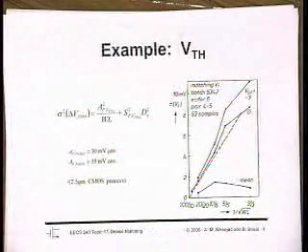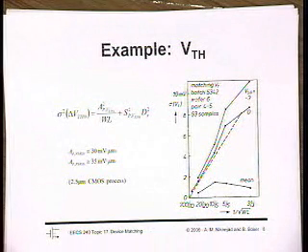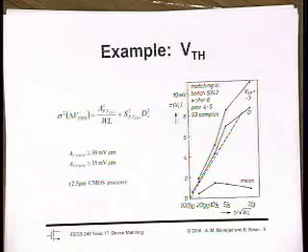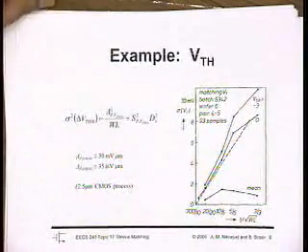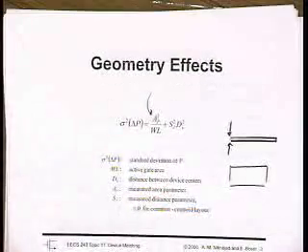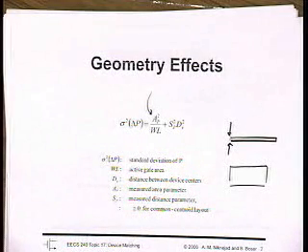This is some data basically showing you that you get a reasonable fit to this equation. Excuse me, I just questioned the previous question. Well, I know that analog uses large W over L, but typically when we do the layout, it's fingers across stuff, right? So it looks like for the single transistor, the L is still the minimum size. How, right?